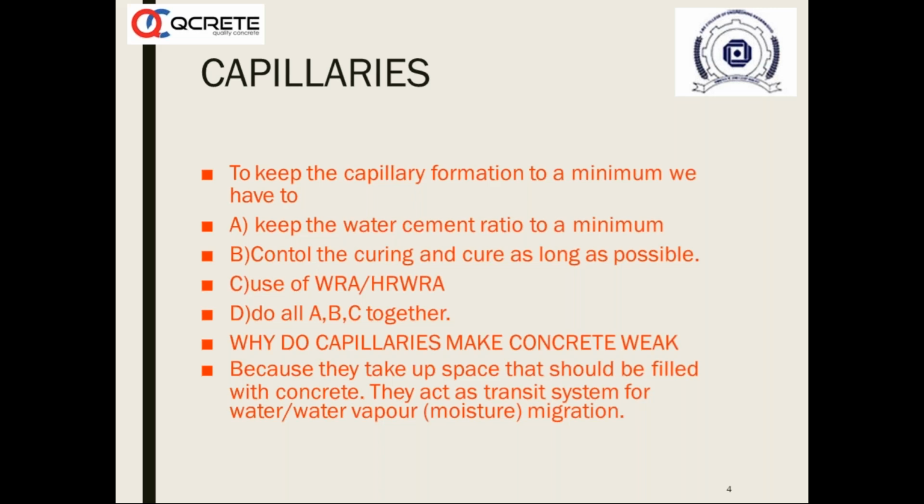So what we should do, we have to keep the capillary formation to a minimum. Keep the water cement ratio to a minimum. We have to add only an adequate amount of water to the body of concrete. We should not add excess water. Control the curing, cure as long as possible.